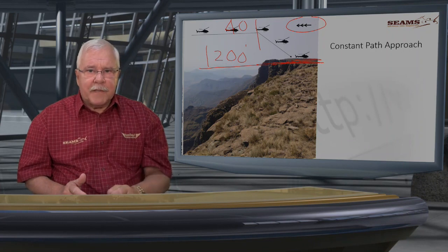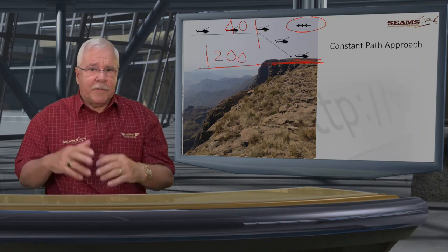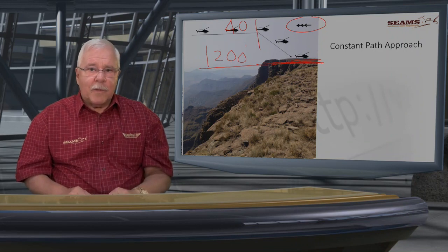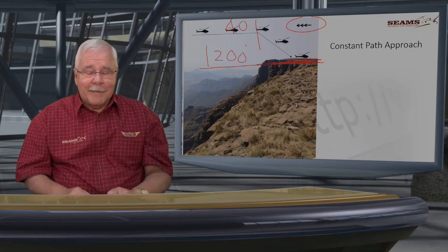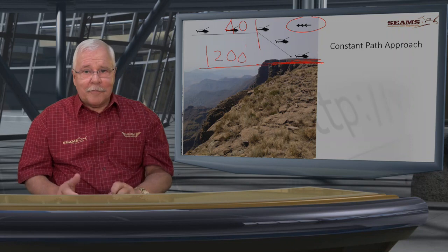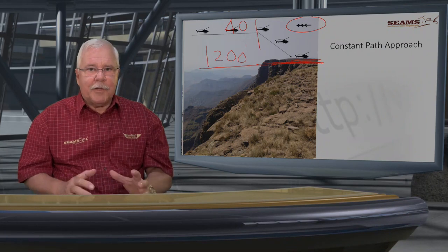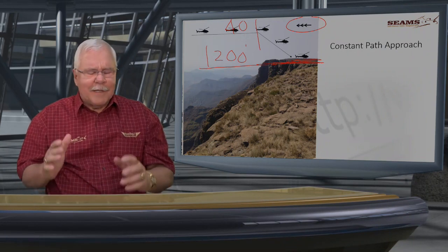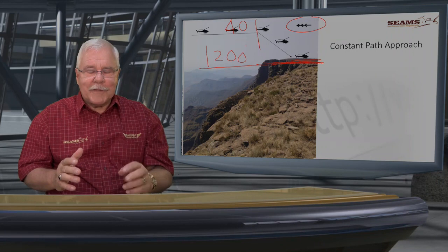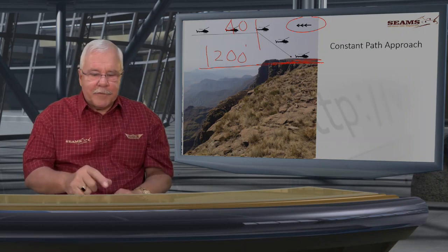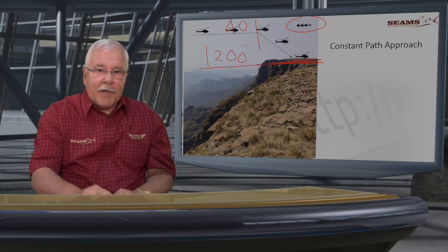Most of the single engine fly-out capabilities of your Super Pumas and so on will be guaranteed at max all-up weight at a speed of 45 knots. I promise you, 40 knots is good enough. A 40 knot approach. Make it 45 if your machine says so. It's not going to make a huge difference. But at the end, you're going to have to break the speed.